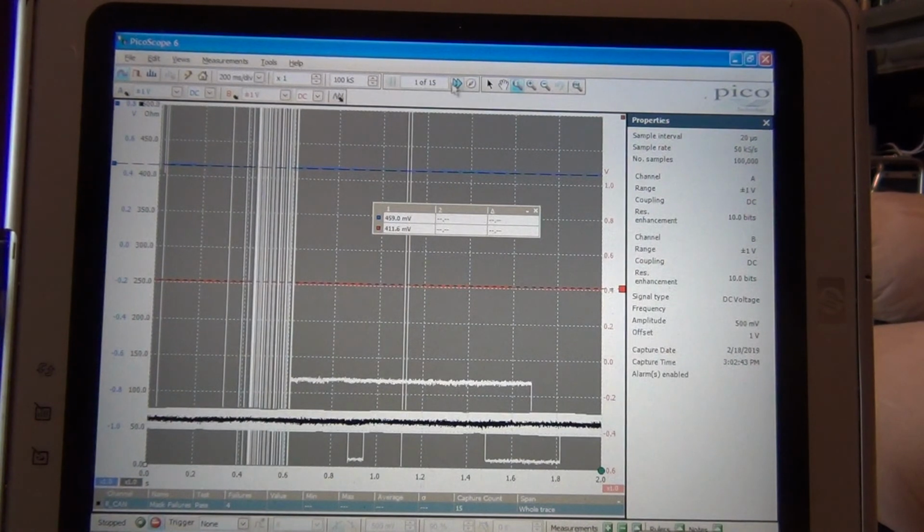Okay, starting from screen number 1, there is nothing abnormal happening for a few screens, but then we get this guy. So our value for resistance goes through the roof, and that corresponds to channel A dropping down considerably, but not all the way to 0. Channel B is the one that goes all the way to 0, which corresponds to CAN low being shorted to ground.